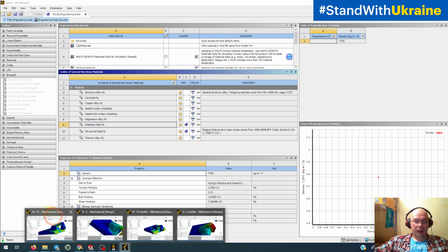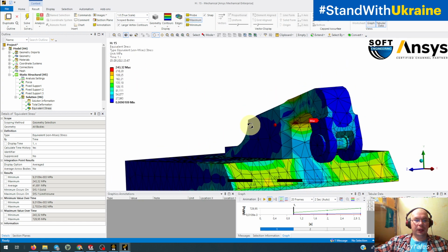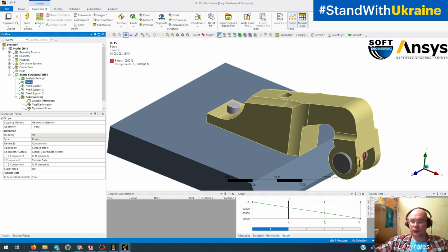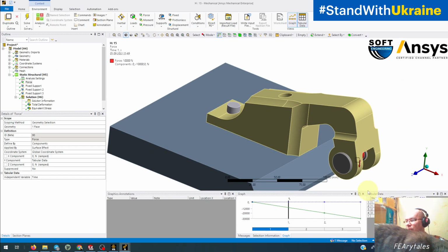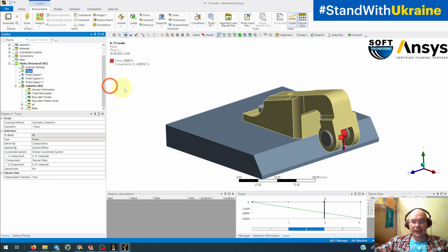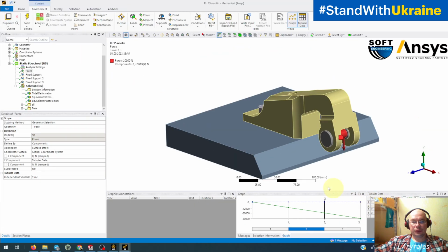So, if we take a look at this result and we see 243 megapascals, we can think that for the first task with a force around 10,000 newtons, we will not obtain any plastic result, any plastic stress and strain. But if we take a look at the nonlinear task, we also can see that we have similar forces. So for the first second it's about 10,000 newtons.